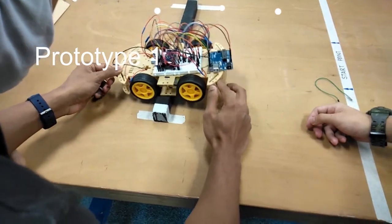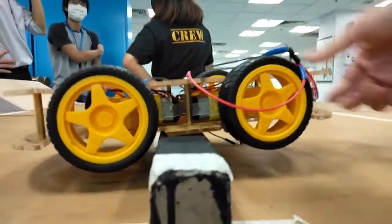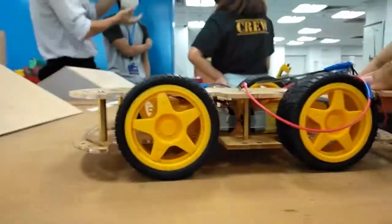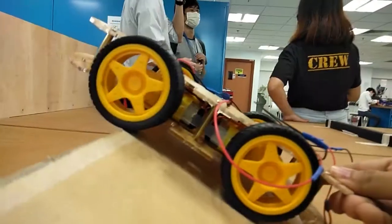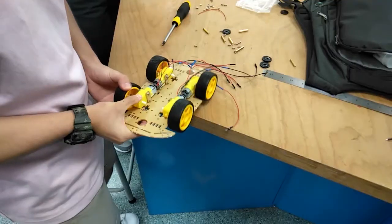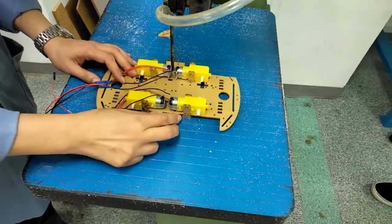Prototype 1 was unable to clear the obstacles because the bottom chassis was too low. Collisions with obstacles would occur. Hence, we concluded we need to make changes to the chassis and increase the distance between the wheels and the axle. We removed the bottom acrylic chassis and made modifications to the top acrylic board.